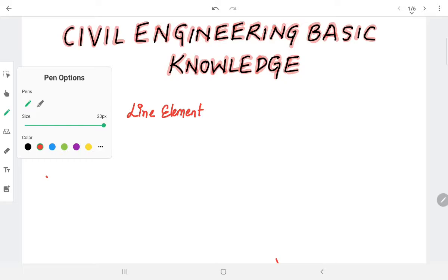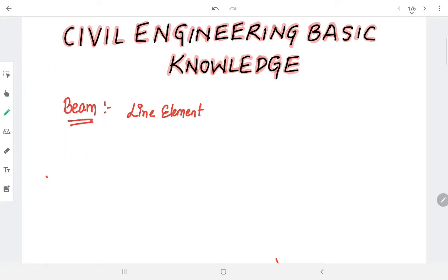Any steel structure member can also be called a beam itself; purlins and such have different names. When it comes to a beam, the depth of the beam mainly depends on the L by D ratio. It is nothing but the length to depth ratio. The ratio is from IS 456.